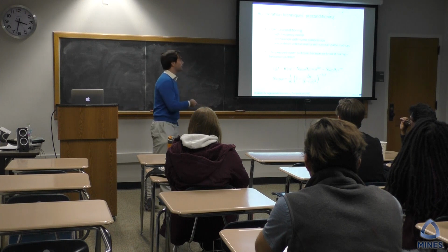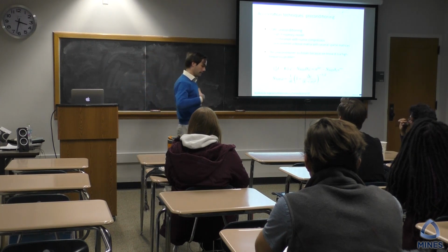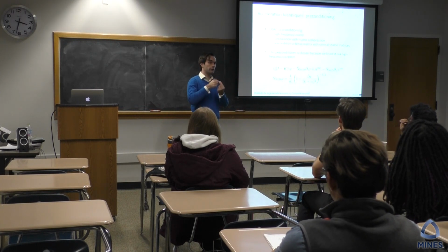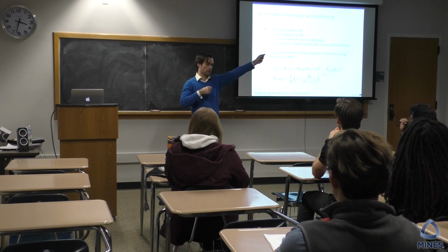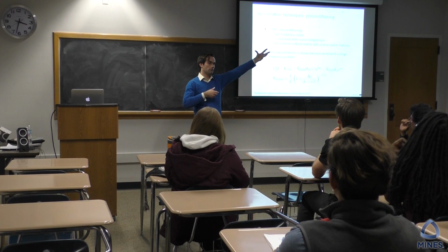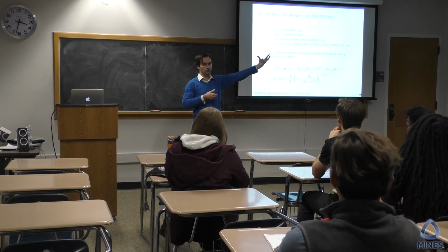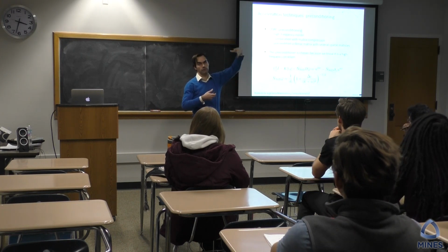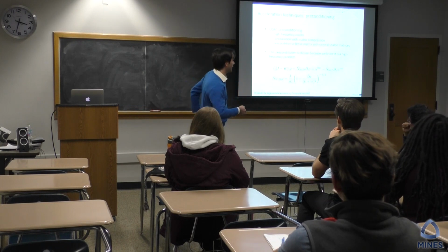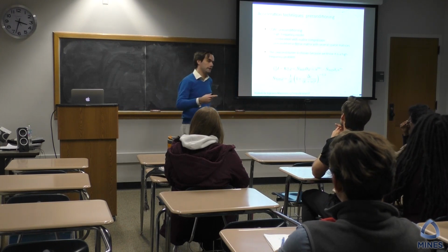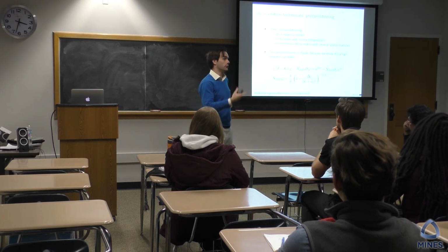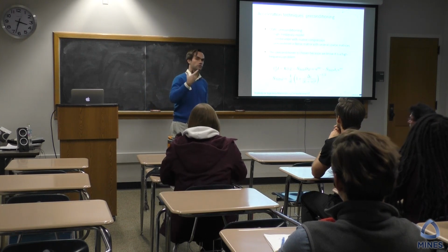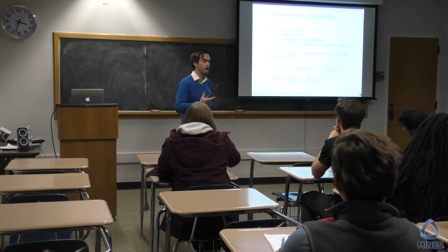Anyway, so why does this preconditioner work? This preconditioner is designed for a high frequency model. So if we take the model and take the frequency to infinity, we can do some approximations. So for frequency infinity, we have some approximations and we use this as a preconditioner. No, we're not at frequency infinity, but we are at very large frequencies. So very large frequency is almost infinity. That's why it looks like the matrix A. And that's also why this works, for instance, for the ultrasound, but not for the bubbles, because that's low frequency. So we choose this preconditioner because we know we have high frequency, so we use a model that's based on frequency infinity.